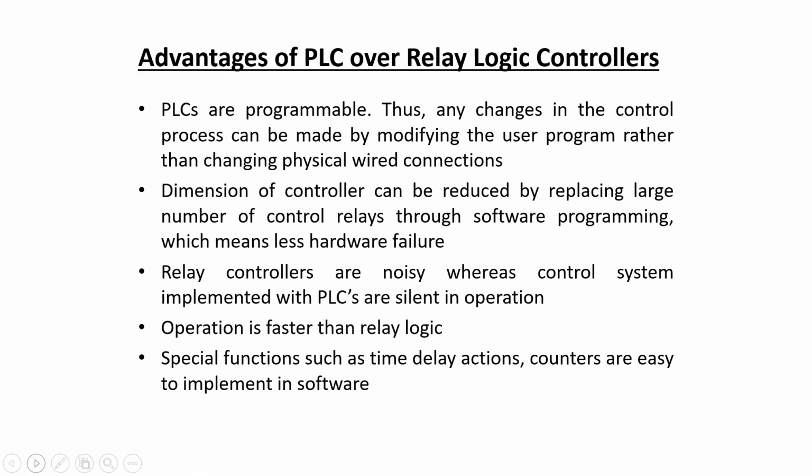So to make the control system process easier, the PLC has some advantages over the relay logic controllers. The first one is that PLCs are programmable. Thus, any change or modification in the control process that you want to make, you can just do in terms of the program.